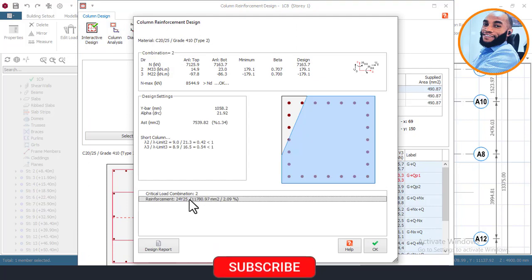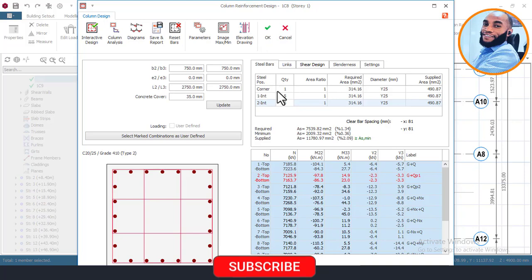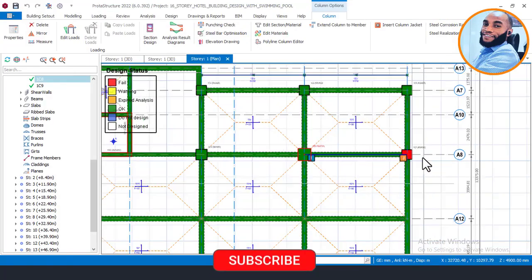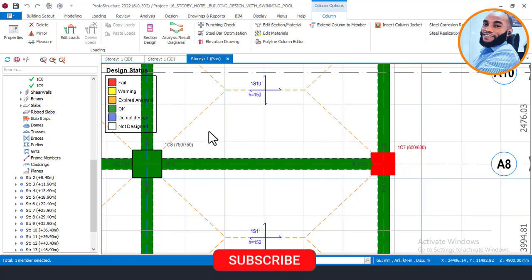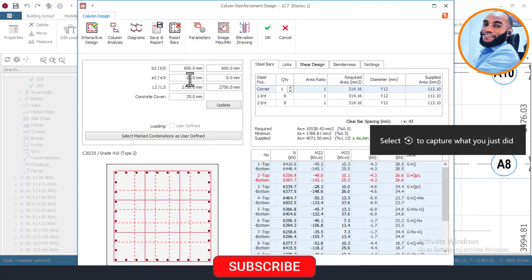Okay, so before, when we used 700 here, I was showing the number of bars, so that was why I went to increase my column to 750, just to reduce the number of bars it's meant to use. Okay, that's fine. So I'll click okay, and then final okay here. Okay, that's fine. So right now again, I'll check here again, right click here, properties, click here, and then reset bar first, and then design.